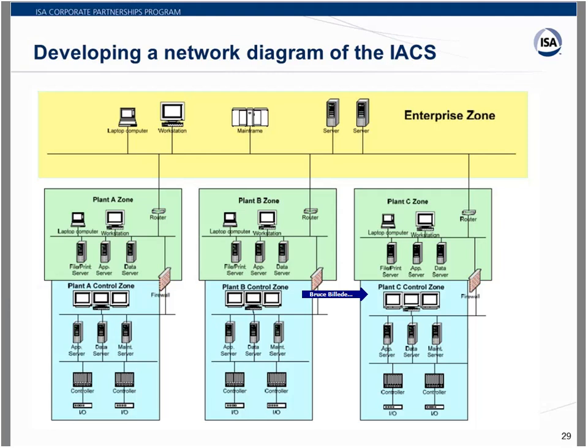If I'm going to put in some monitoring, and I've only got so many points I can monitor for a certain cost, I'm going to focus on this latter section instead of on plant A, where I have more time for recovery. So it's really important that you break that down into cells when we're talking about loss of production, if you have a large enough plant that occurs.